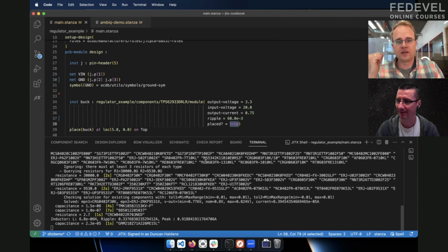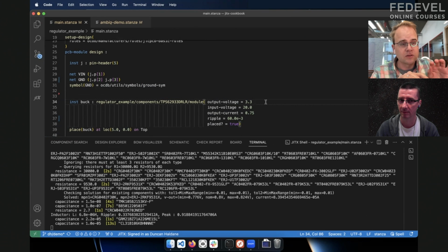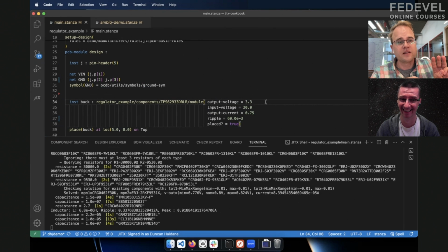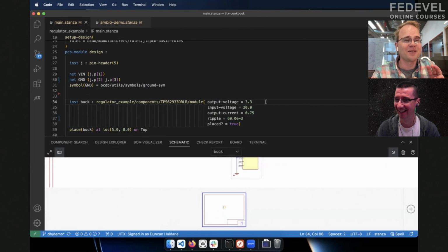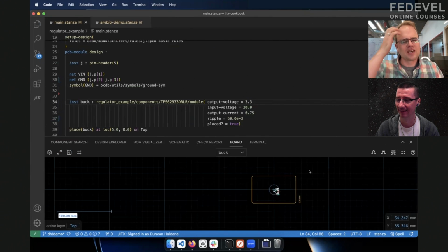So that's a voltage divider that under all variations of operating temperature, including the TCR, as well as manufacturing tolerance, the combination of these two resistors will produce the correct feedback voltage. And then it also makes sure that each resistor value is triply sourceable. Because you don't want to design your feedback network using some $9 resistor.